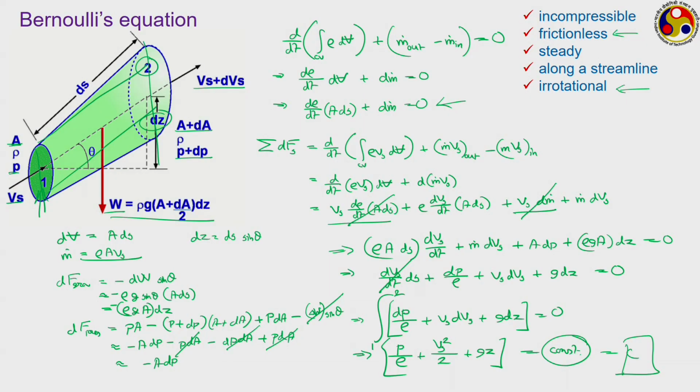But frictionless is a quite idealistic assumption, because every fluid has some viscosity of its own. So there will be shear stress and there will be shearing losses. To take care of the shearing losses, quite often we have to add a corrective factor into this equation. We may see examples for that very soon. But let us now move to our discussion on flow measuring instruments using this concept of Bernoulli's equation, and for that first we have obstruction meters.